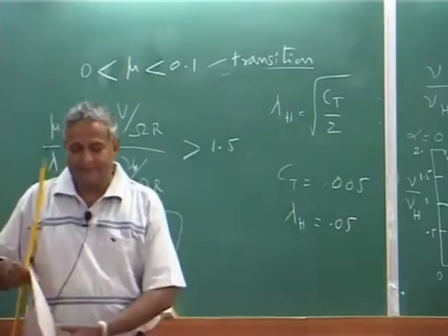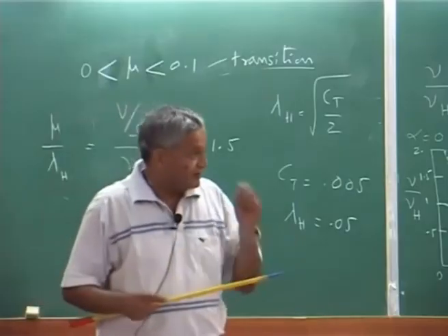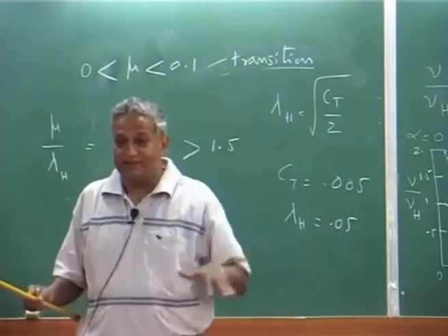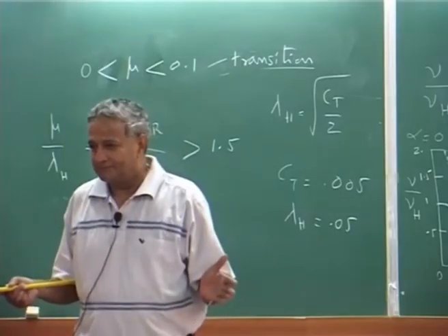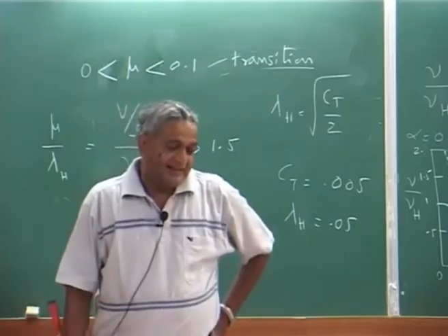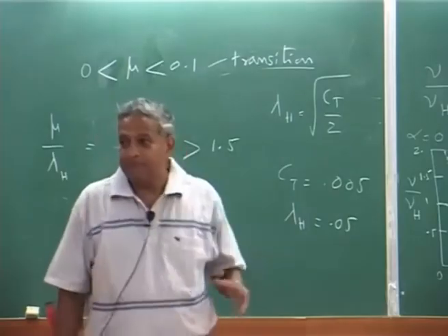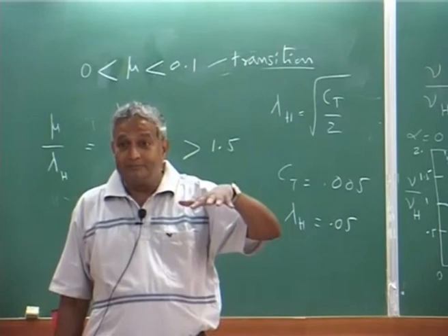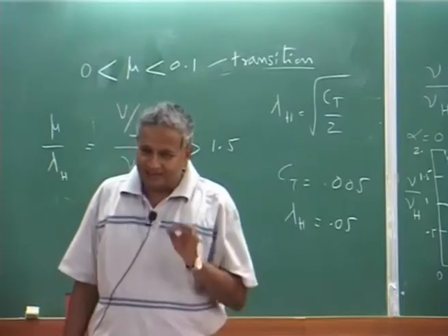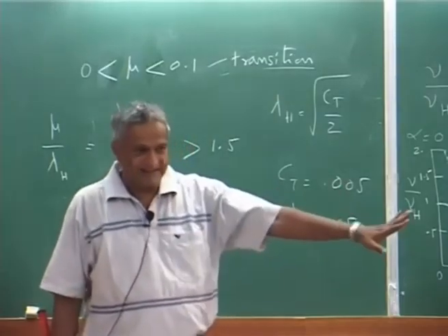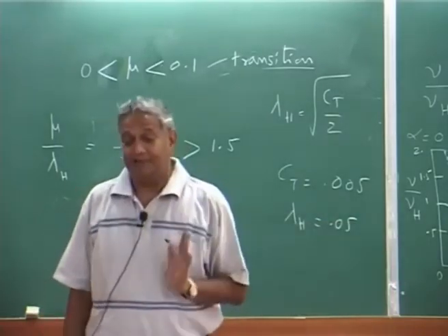Okay. So you find that in this zone, 0 to 60, you have a lot of variation in the vibration, but the important thing is the rotor behaves like a circular wing, and I said aspect ratio is very small, and as a result there is a lot of variation in the inflow. Our assumption of uniform inflow over the entire disc is not really valid, because you have done one homework. Even in the hover case it is not, but in forward flight it is even more so.